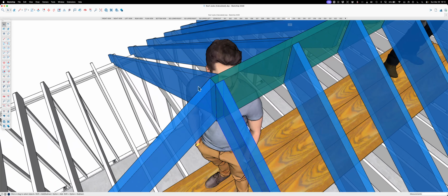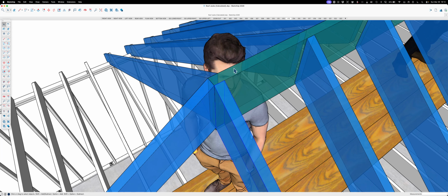So we're going to zoom in here. This is how this should look. I use Chief Architect a lot to do plans for permit, and in their software, this ridge ends in the middle of these 2 commons, which is part of that whole dotted line string theory layout, whatever that is. But it needs to come out here, and then that way this and this and this, they're all the same. They're all the same rafter.